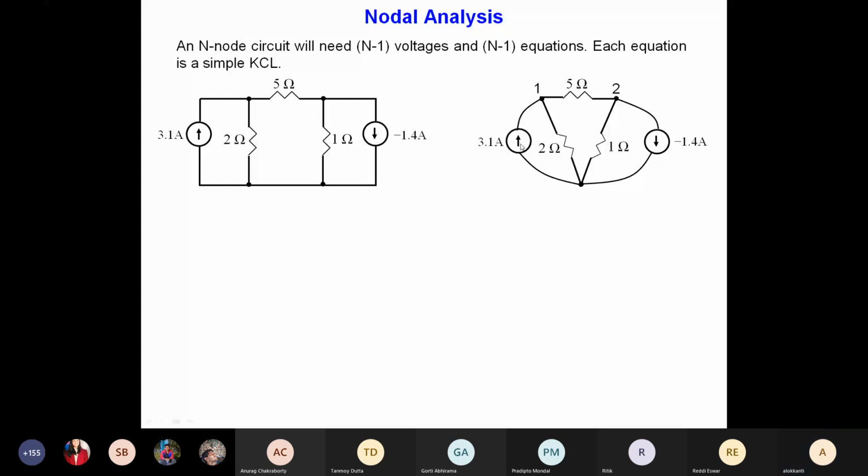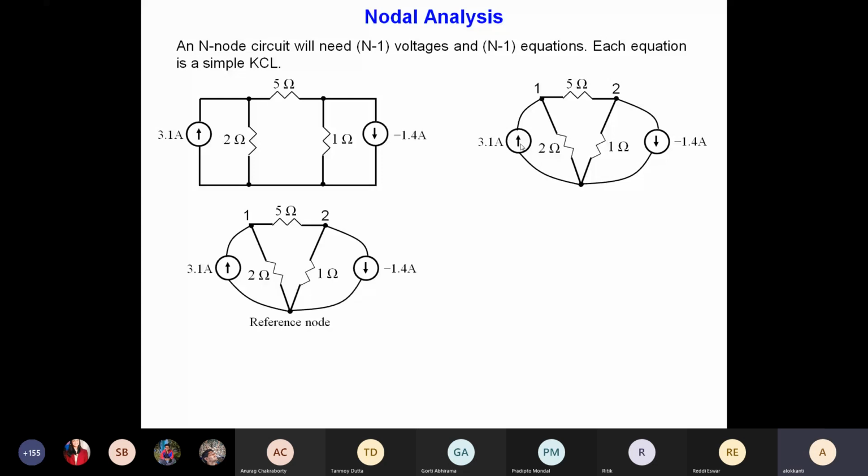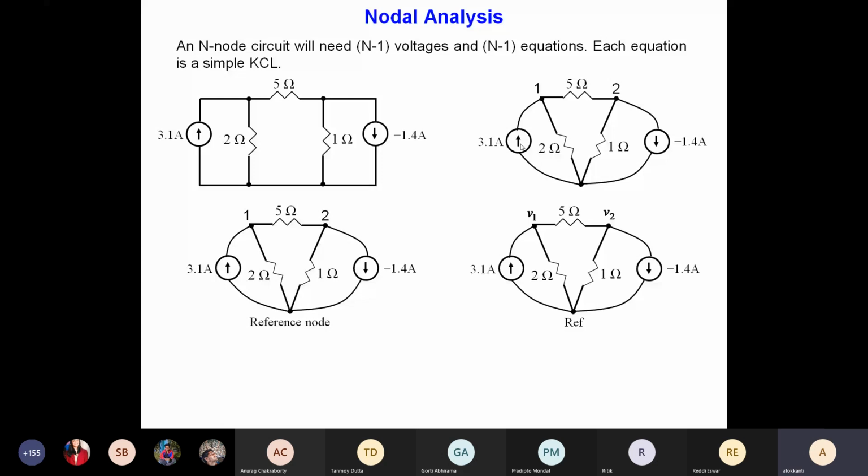And then we give the existing nodes some voltage values, and by deciding the directions, we write down the KCL equations correctly. Obviously, correctness is required in the KCL equation. If you write your equation wrong, then your entire final answer will be wrong. So you have to follow the step-by-step procedure, give the directions, and then follow those directions and write down the equations correctly.